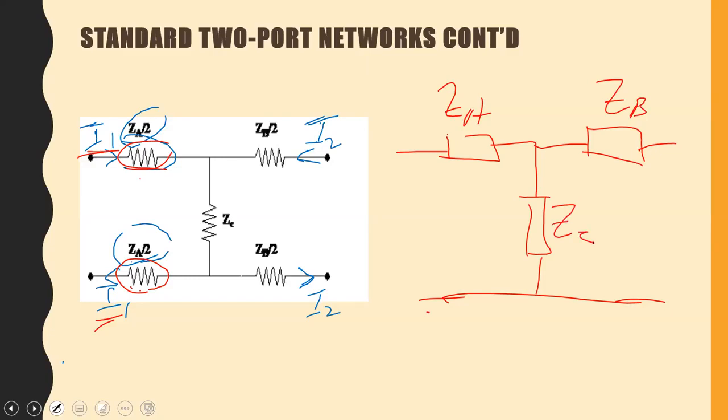So in terms of balance, what we are saying is that the impedance seen on one terminal would be the same impedance seen on the lower terminal, as drawn here on the right. Yes, it is unbalanced because I1 encounters an impedance ZA for that terminal. We know that I1 is the same, would be coming out here.